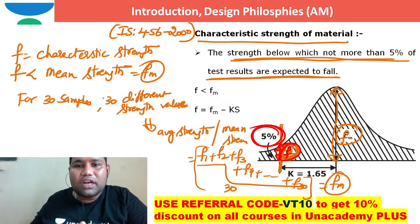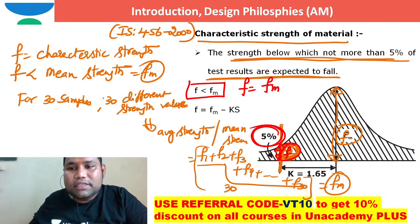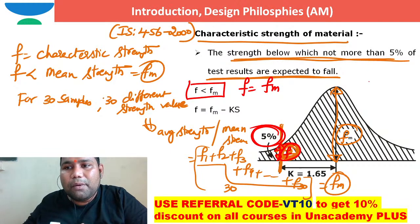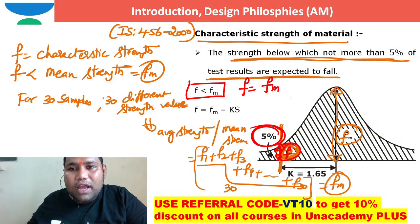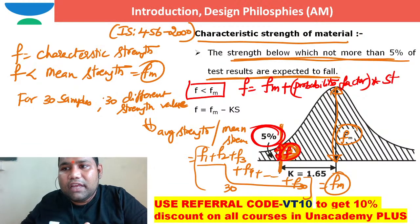So how can I write that? As f is less than fm, I can write the characteristic strength f as the mean strength, which is at a 50 percent probability that the test results will not fail. To get the 5 percent strength, it is the mean strength minus, or plus, a probability factor multiplied by the standard deviation.